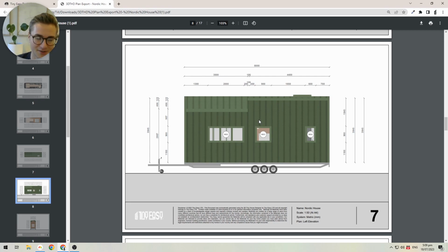And again, just another thing here, what you'll see, you have a 1.1 meter sill height for all of these windows, and all of the windows are also 900 millimeters high, meaning that they all line up, and because of that you get nice clean dimensions. If you have windows that are jumping up and down and you've got them at different heights, you might have a lot more dimensions popping up here, so you would just need to understand where the windows are placed.